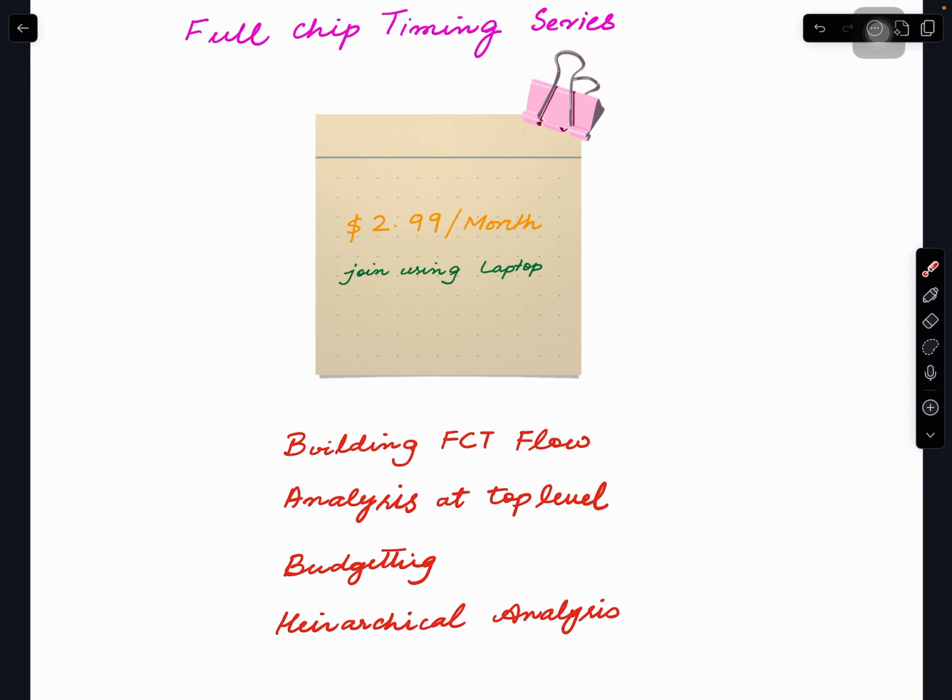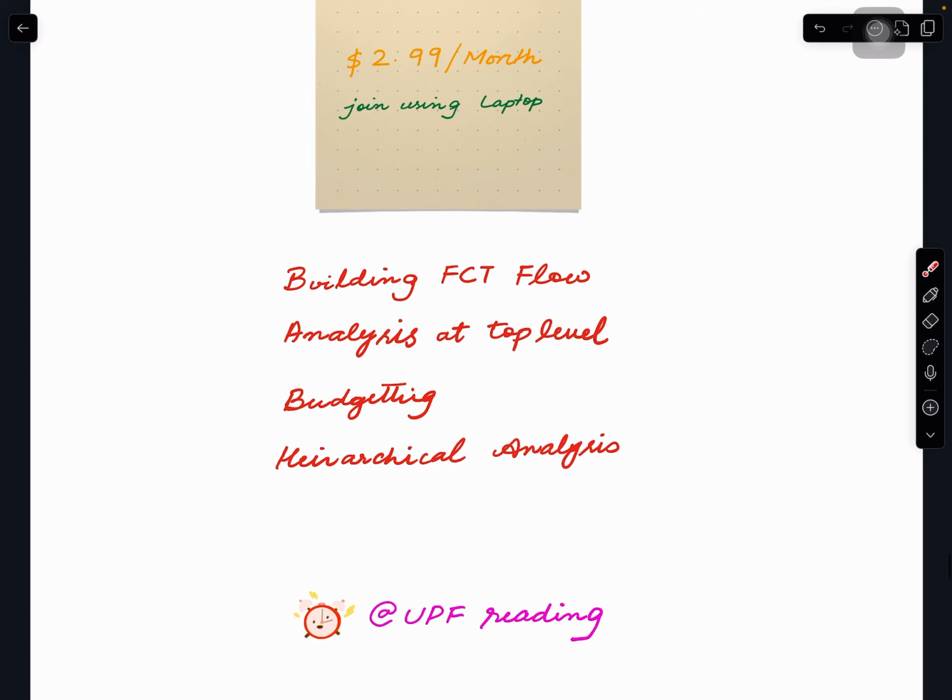Once we build that, the goal is also to understand each stage. For example, right now we are at the UPF reading stage. And I didn't want to just say, okay, we read UPF and then move on, since I didn't give any background on UPF prior to this on my channel. So I'm going into multi-VDD power domain.